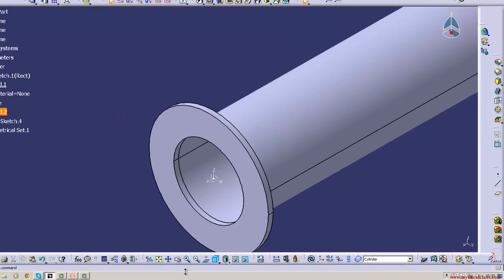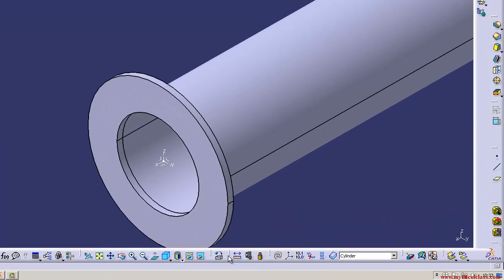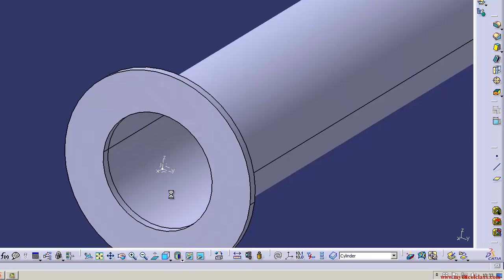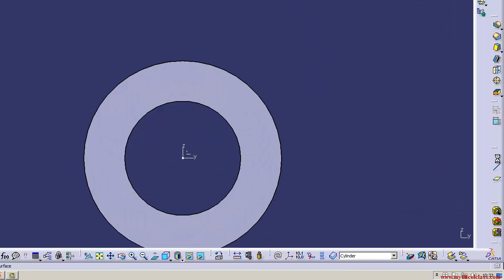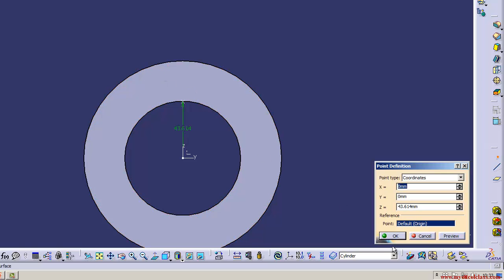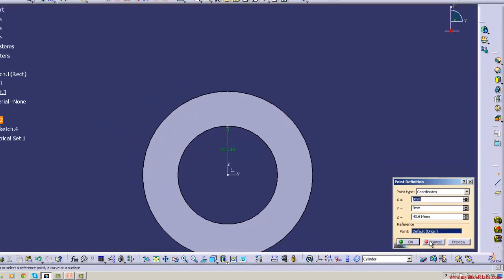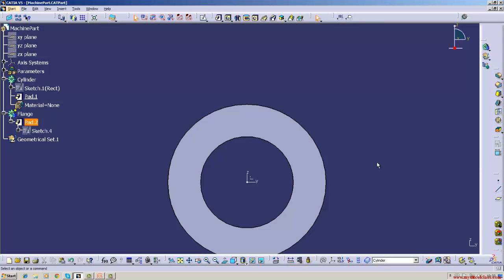See, this we created in the regular plane, that is in the 3D plane, using the hole command. We created it like this, and we assigned the hole values and the point, the coordinates we gave them, and then we created a point, and there we drilled the hole. Now on the sketcher plane we can also create a hole by using the pocket command.